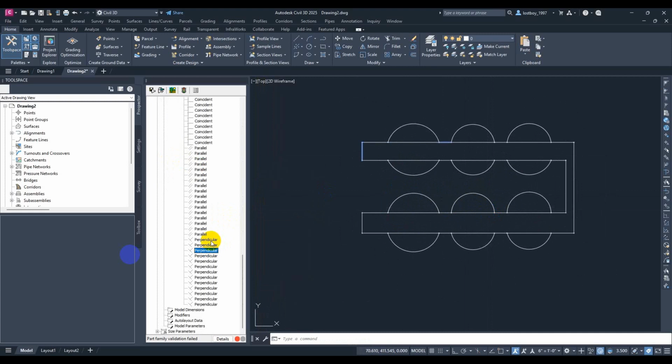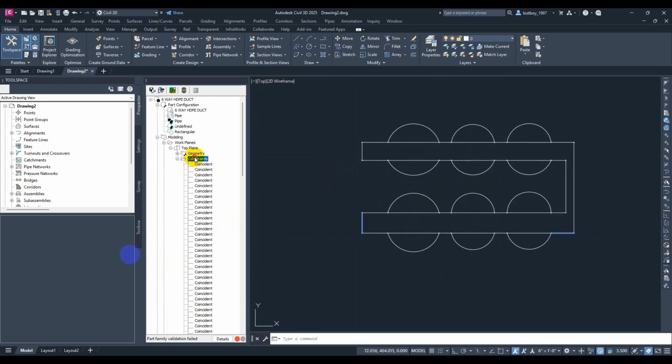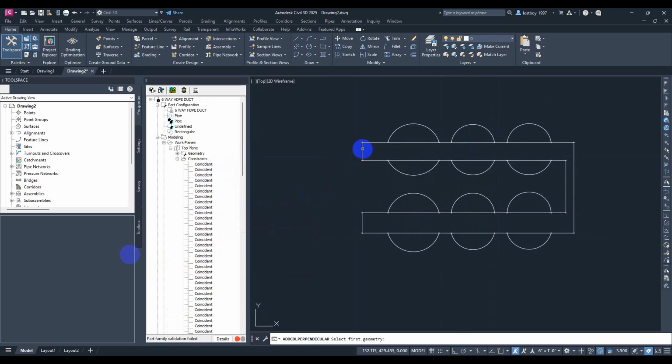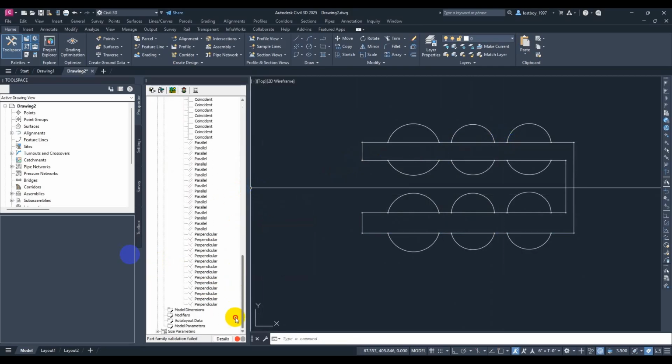Let me check the camera, just to make sure that everything is correct and we didn't miss any. So see, we missed one line. This one line can make terrible trouble for us. So we have also to add this constraint to be parallel. It's very important with the constraints. You have to make sure that everything is considered, you didn't miss anything, and all these parts are connected together. So now we added it, and we made sure that the parallel and perpendicular constraints are correct now.